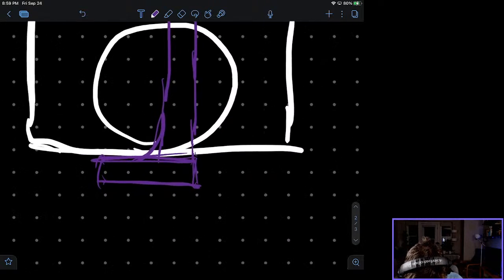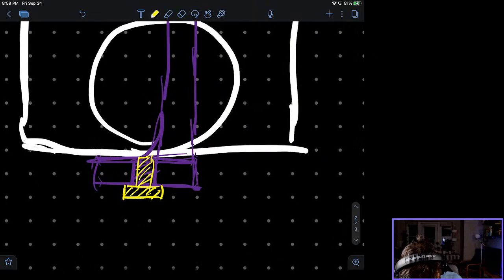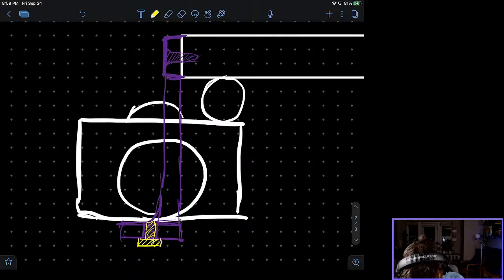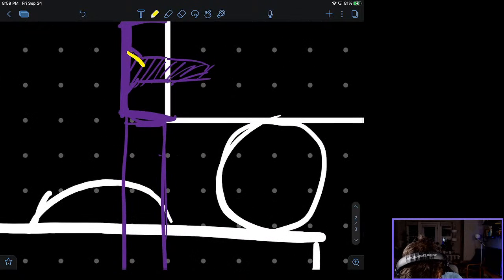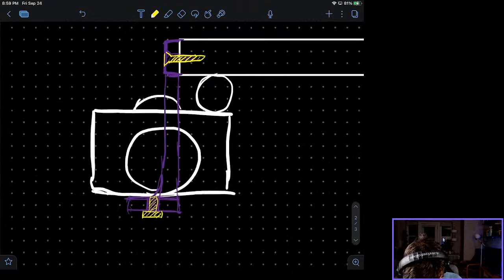And here is where I add in another hole so that we can add in a screw. I'm going to make this a screw head like this. That goes, and so it's a 1/4 inch 20 that'll go right into the camera, and that's where I'm going to screw it in.